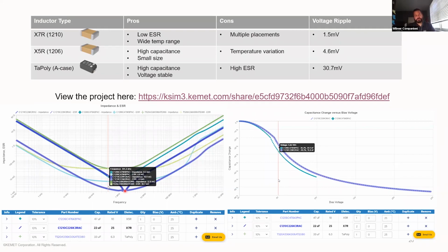But I guess for those that may not be familiar with the actual mechanics of construction of a metal composite inductor, it starts off as metal powder that is compressed along with an organic binder into that shape, and it is not a sintering process.